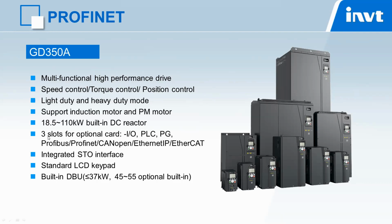Above 7.5 kilowatts, it has 3 slots for optional cards: I/O cards, PLC cards, PG cards, Profibus, Profinet, CANopen, EtherNet/IP, EtherCAT, and others. There is an STO terminal on the control board. All the inverters come standard with an LCD keypad. Below 37 kilowatts, it has a built-in DBU. For 45 to 55 kilowatts, it's optional, built in with a dash B behind the model.